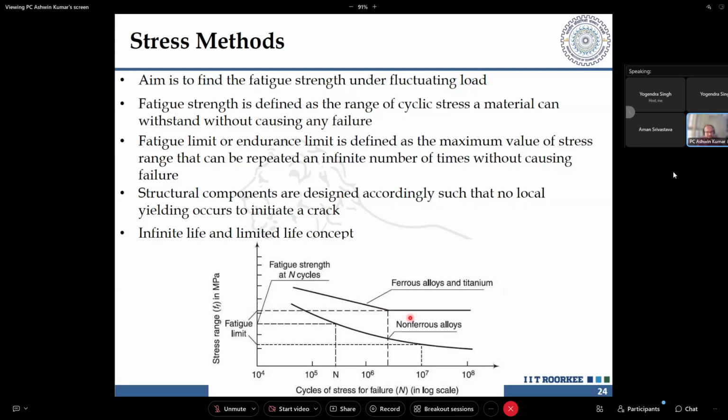But if I am looking at a gantry girder, whose problem example we are doing, we understand that it will be operational a certain number of times in a particular day, and that will be done over the years, and the service life of the building might be 50 years. So you expect a certain stress range to be developed in that particular detail category, and then we know how many cycles it can survive.